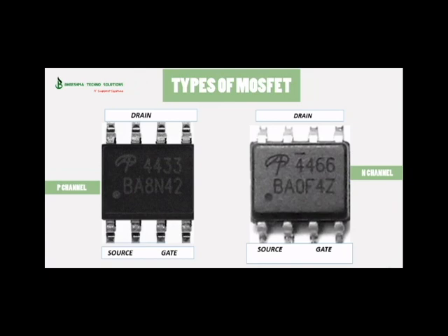It will pass the supply from drain to source when we apply a signal at the gate. If we apply a signal or voltage at the gate, it will pass the voltage to the source. If the gate signal is missing, no voltage will flow, thus acting as a switch. The input can be either drain or source depending on the circuit it applies to.